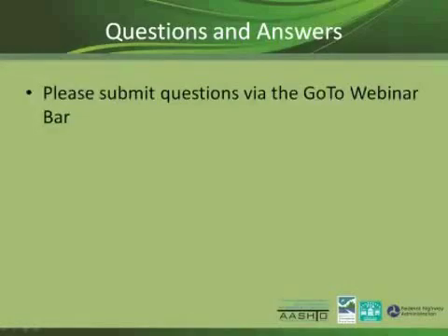I think, Lee, you were the one talking about 2 inches per hour infiltration. What was the underlying soil like? So the underlying soil is very infiltrative. I remember it was like 20 inches per hour or more. So if it's very infiltrative, it will not treat the water to the level that we want. So we have to slow down the infiltration a little bit. So by doing that, we have to bring in a compost amendment soil and compact it a little bit to slow down the infiltration. Okay.